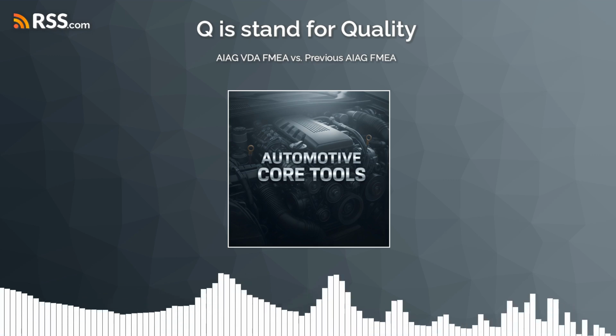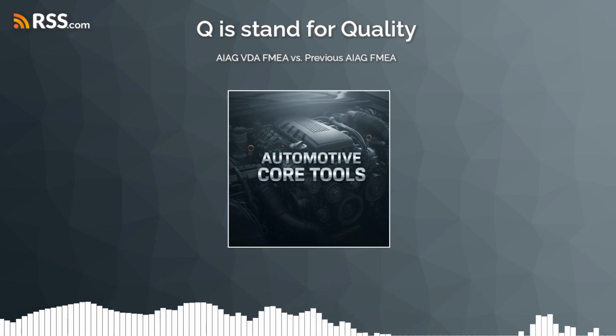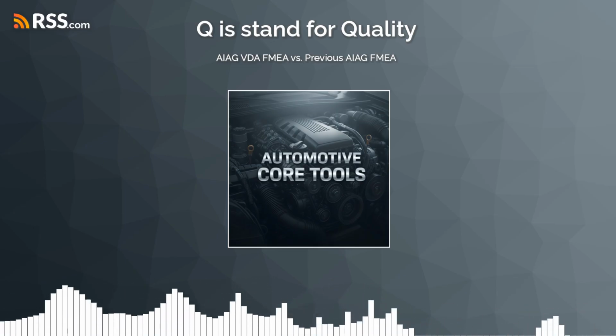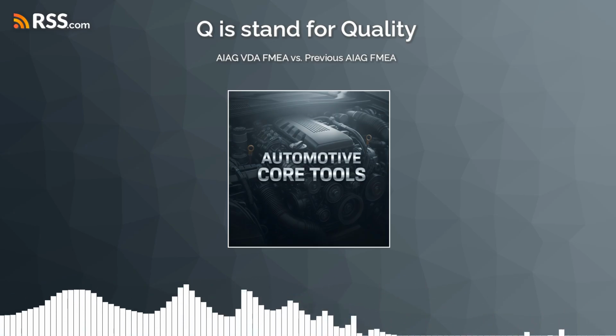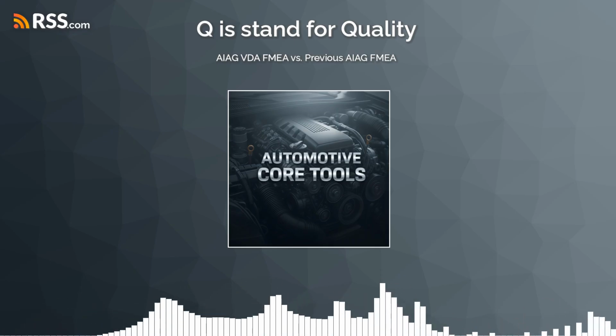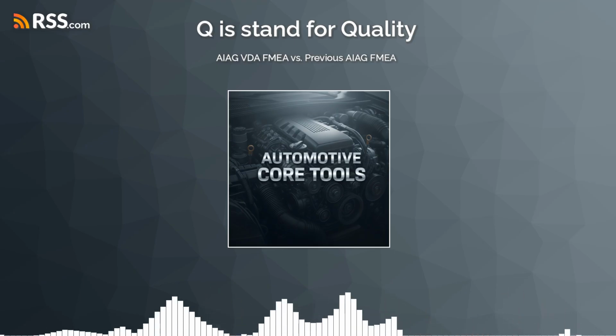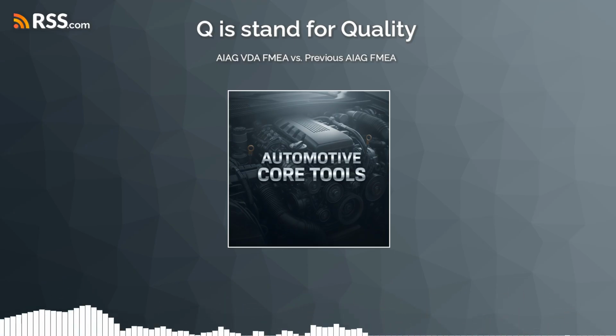Okay, just to be crystal clear for everyone listening, can you briefly summarize again the core difference between a DFMEA and a PFMEA, and why an organization really needs both? Sure. Think of it this way. DFMEA is about the thing, the product design itself. What could fail because of how it's designed? Are the tolerances right? Is the material suitable? That kind of thing. Okay, the design.